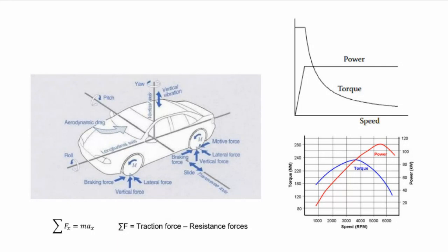The most restrictive condition will determine the maximum traction force. If you want to design an electric vehicle, first step, you need to calculate maximum traction force. Okay. Now, the drive system includes vehicle engine or vehicle electric machine, also gearbox and power transmission system.